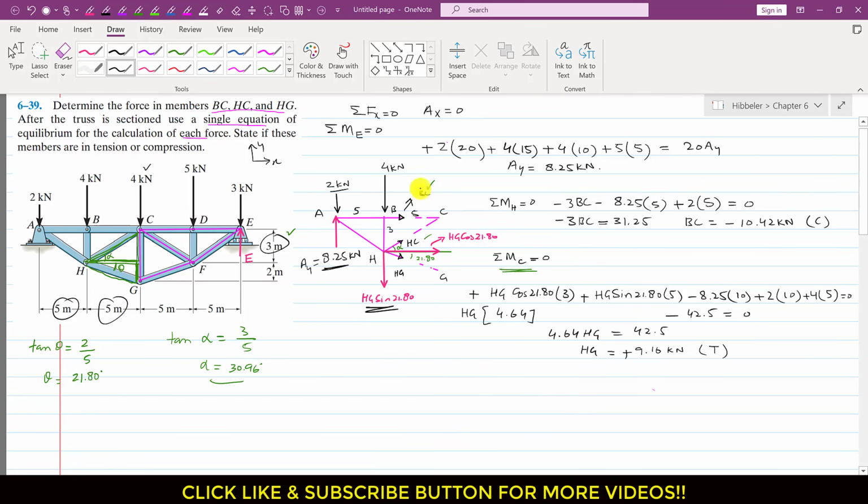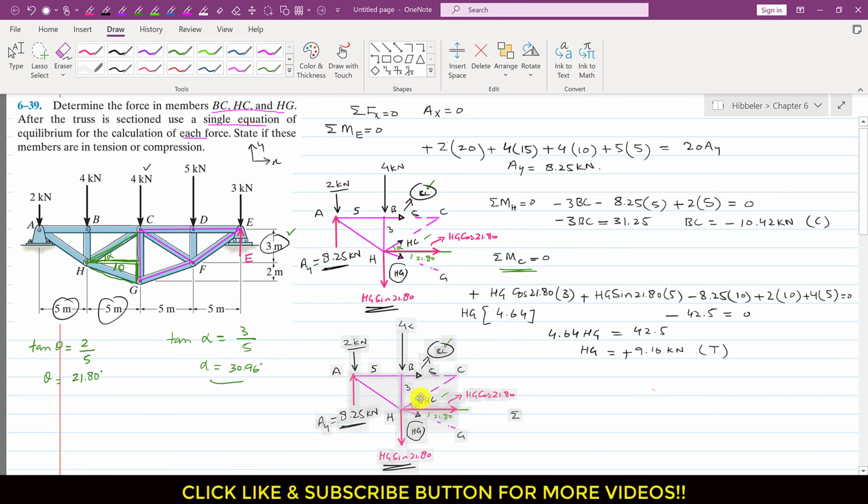Now we have determined this BC, we have determined this HG, now we are left with this HC. And again we need to write an equation which needs to have only this HC as the unknown force, right? So now we have to select a point where the line of action of this BC force and this HG force pass, and we have to find the summation of moment about that particular point, right? So for that, let me enlarge this free body diagram. We need to have the larger view of this free body diagram.